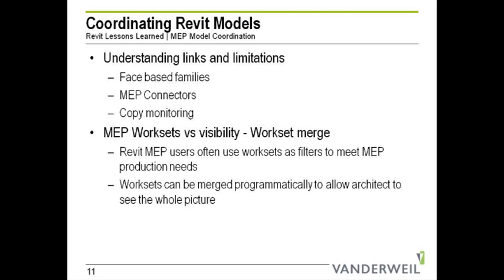But, for example, one thing that differs is if I was going to put, say, a light fixture into an architectural ceiling, in a hosted model, it will actually cut out a hole in the ceiling for that light fixture. It will align itself to the grid, that kind of thing. In a linked model, you can use alignment tools to align it to the grid, but it's going to be basically poking through the ceiling as opposed to really hosted inside of the ceiling.